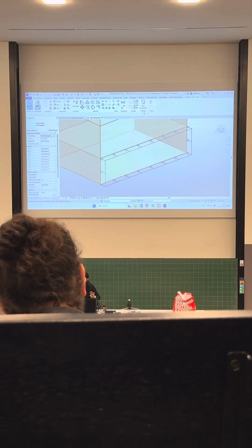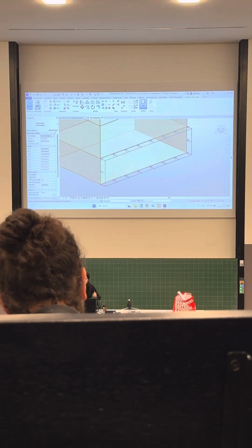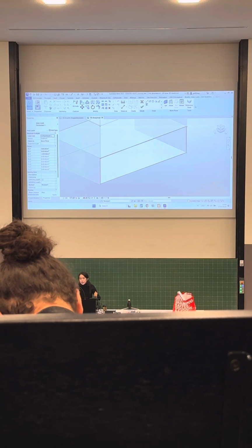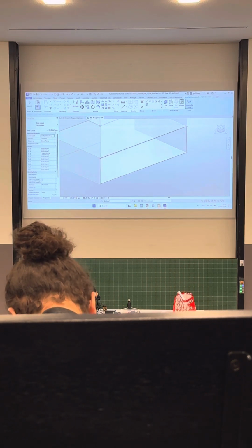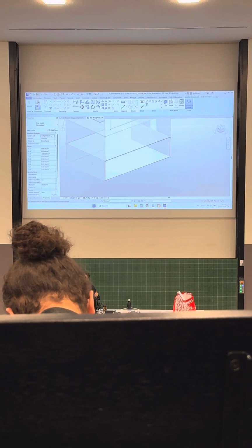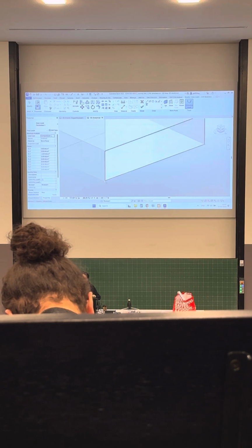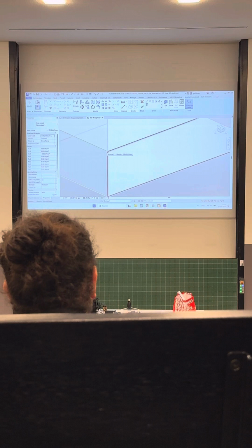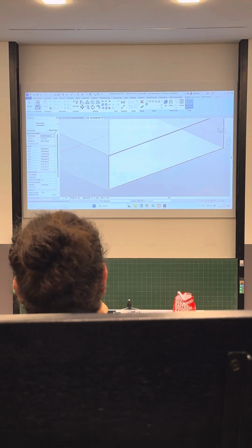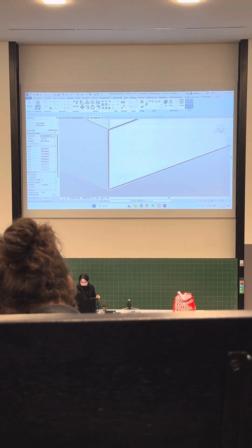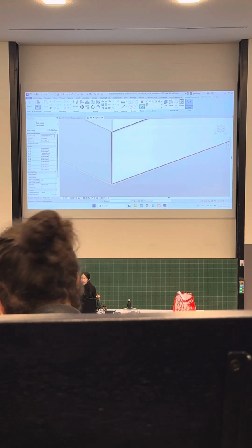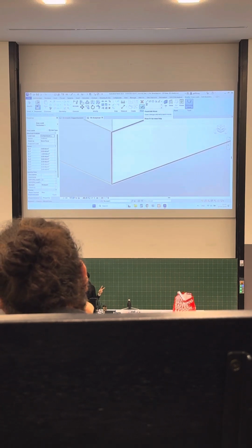You choose any area load that you would like to modify. You click the edit boundary, and there's a tool of reference point. And you define 2 points that you would like to have different values. For example, this one and this one. And now you can see that there is such a small number, 1 and 2 down here. And I click only the 2 because there are 2 different values. And here you can define the forces that will be different.